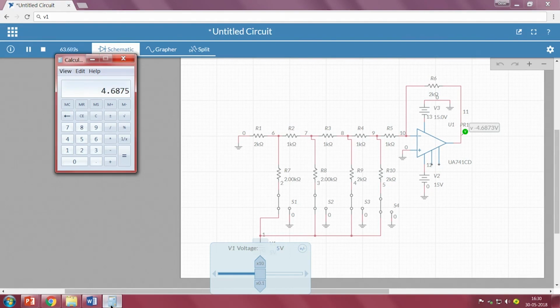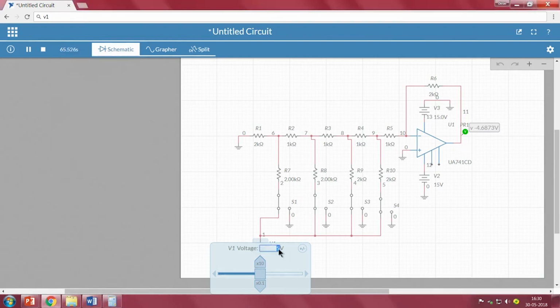So, one important consideration is, whenever you are working with an op-amp, you have to see what the expected voltage is, whether the expected voltage is lower than your saturation voltage or not, right. Now, since we calculated our complete theoretical output voltages using a reference of 15, I am going back to 15, right. That is why it is showing 13. So, we will make it 1110, meaning the D0 bit is 0, but except the D0 bit everything is 1.